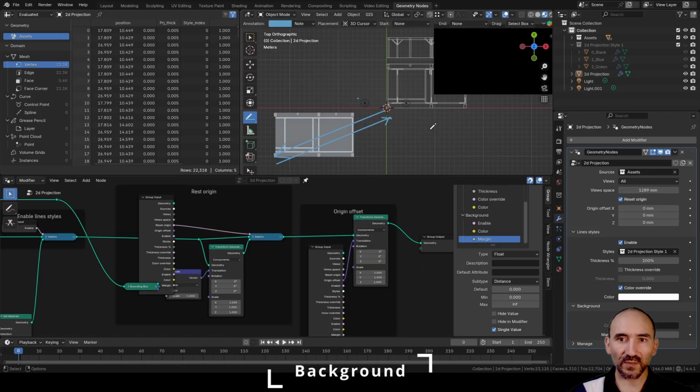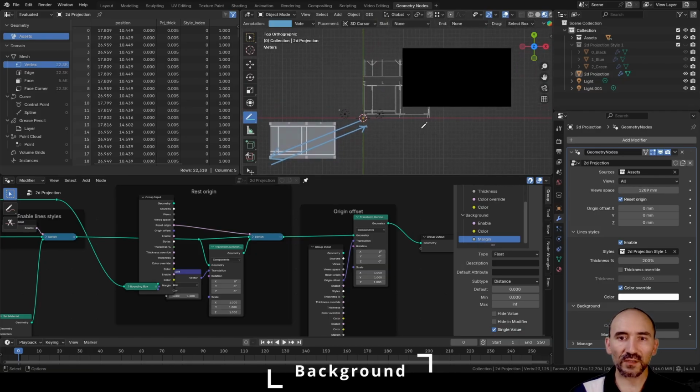And the system now is using the same logic to move the center of the rectangle by the same added vector. And this is why I see the center of the rectangle not here in the global origin point, but shifted by the same amount of length and direction.